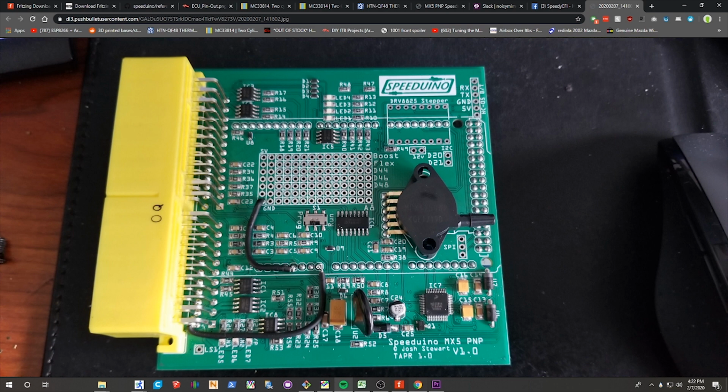So once the Arduino was getting switched 12 volt power, he ran a wire from the 5 volt output of the Arduino to the 5 volt proto rail of the Speeduino to then provide 5 volt power to the Speeduino. Therefore, all the other circuits are provided with 5 volt power just because they're already connected and grounded, and it's already one circuit, essentially. So this was the repair that was necessary to solve my issue with this integrated circuit that had gone bad, which was preventing my car from starting.